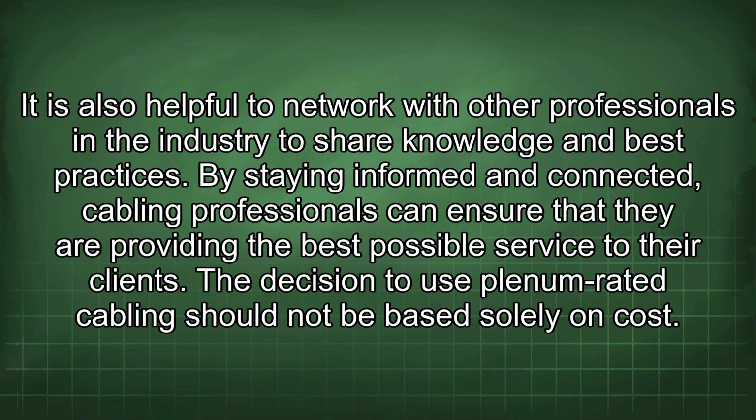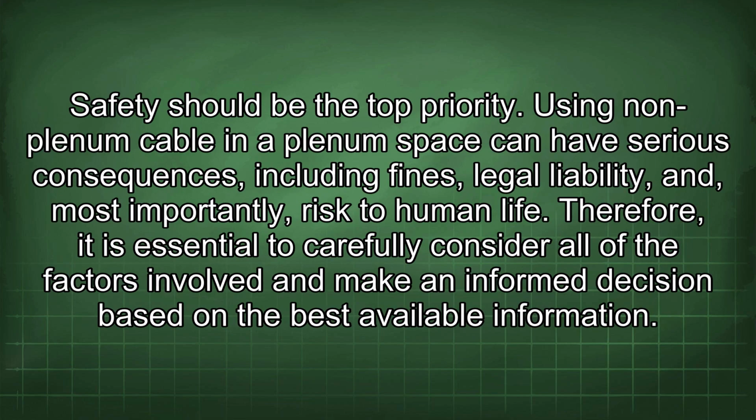The decision to use plenum-rated cabling should not be based solely on cost. Safety should be the top priority. Using non-plenum cable in a plenum space can have serious consequences, including fines, legal liability, and, most importantly, risk to human life. Therefore, it is essential to carefully consider all of the factors involved and make an informed decision based on the best available information.